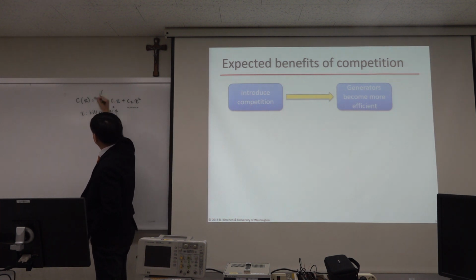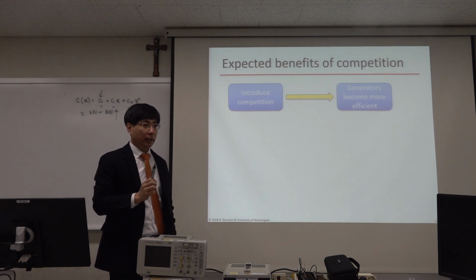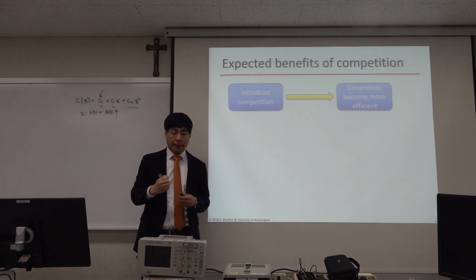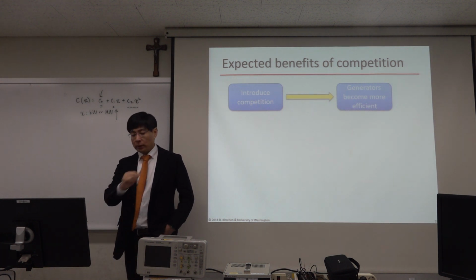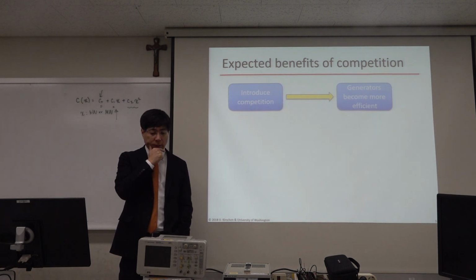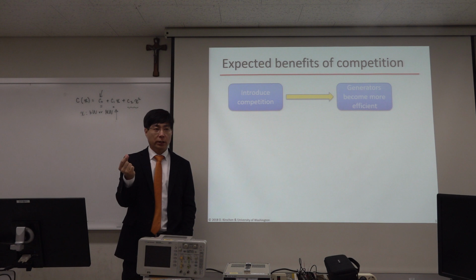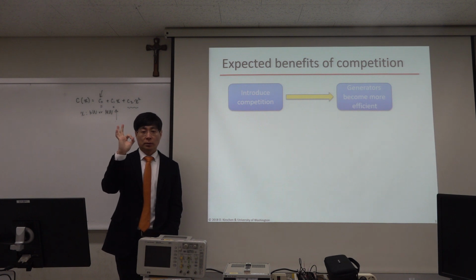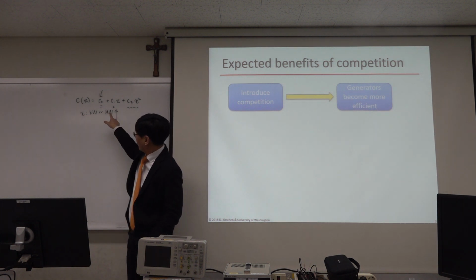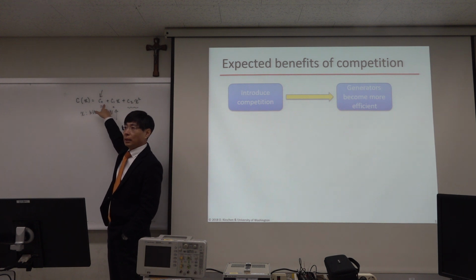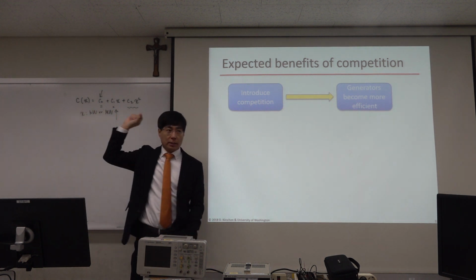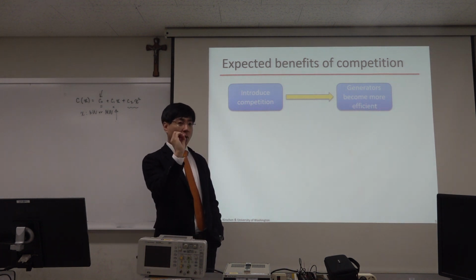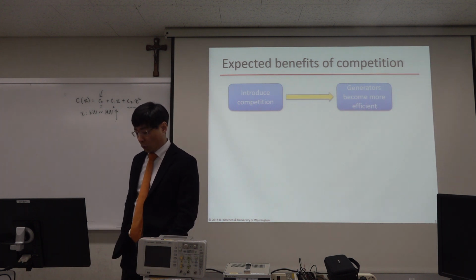But this C0 should not be neglected, because this fixed cost is also important, and is about the decision of turn on or turn off the generators. When the generator is turned on, even if it generates zero power, it still needs to consume some money. Okay? That's the meaning of fixed cost. When the generator is turned on, it generates zero power, but still it incurs some cost.